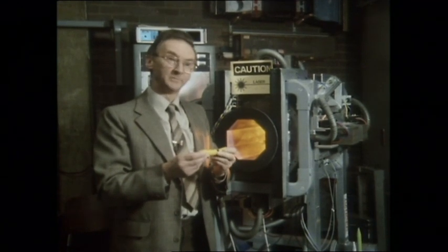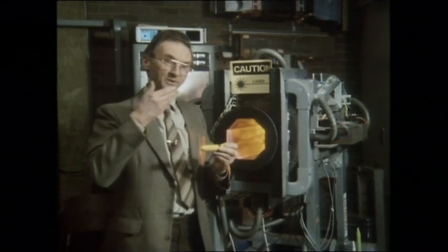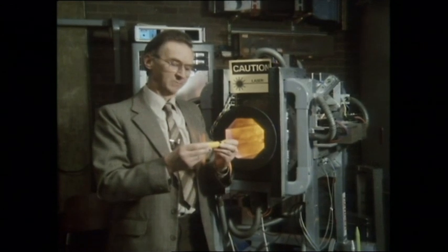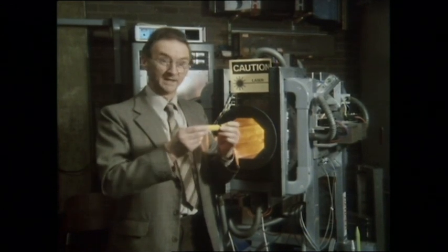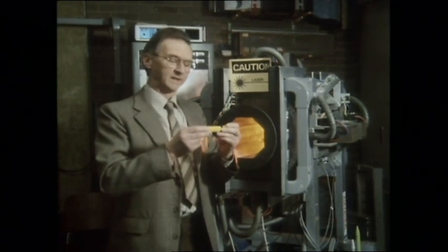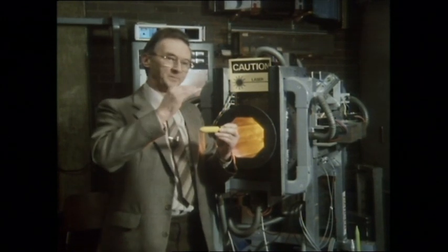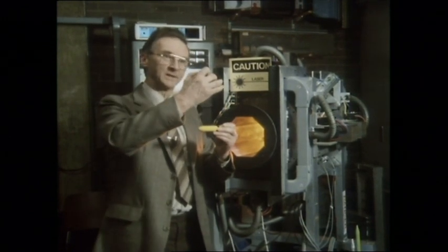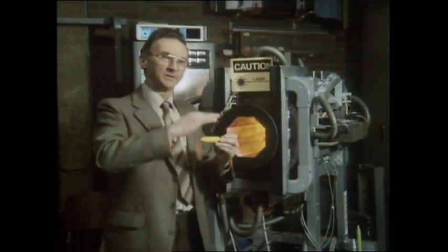So we have to provide a closed loop round the system, so that if the model is, say, too high, then the magnet is weakened and the model will drop down to be in the desired position. 6 slits of light are projected across the chamber. As the model moves about in the beams, optical sensors locate its precise position.